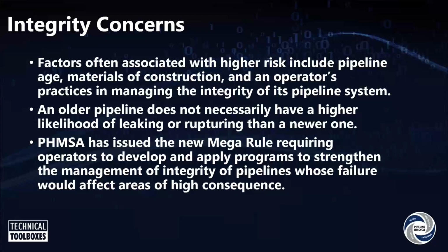I'd like to start off with integrity, one of my favorite subjects. And one of the things that I've been involved in over the years, we actually got started in 1990 by a very young vice president. And that's how I got involved in it. Factors often associated with higher risk include the pipeline age, the materials such as coatings and things of this nature, the pipe itself, the higher strength materials, and the operator's practices in managing the integrity of the pipeline system.